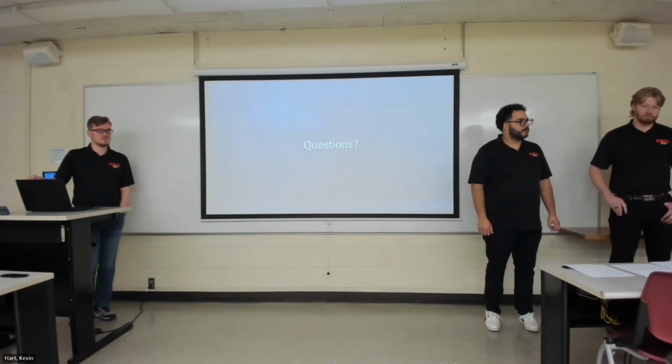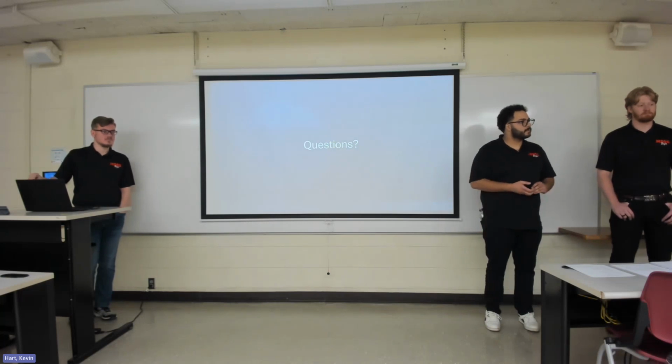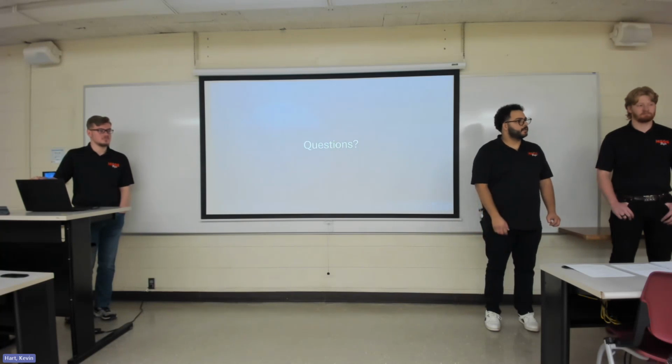Definitely. Where are your loads coming from? And about how much are they? If you're designing a drivetrain, those are numbers you should just have from day one at the top of your head, what's coming in, what's going out. What the speeds are, how they're going.